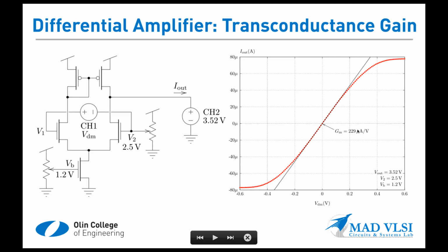And here there's a new quiescent output voltage, which is where we're fixing the output for this voltage to current transduction curve. You can see that with the above threshold bias, we have a wider linear region before it saturates, and the slope of the tangent line here is 229 microamps per volt. Alexa, what is 0.229 times 454? 0.229 times 454 is 103.966.